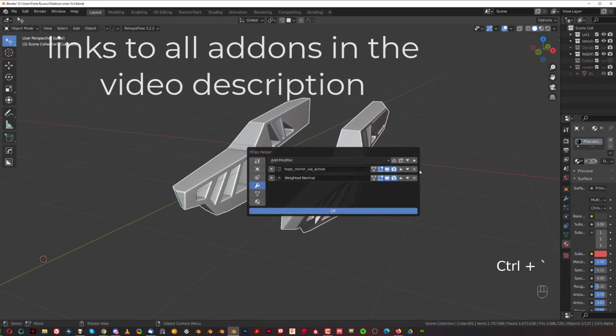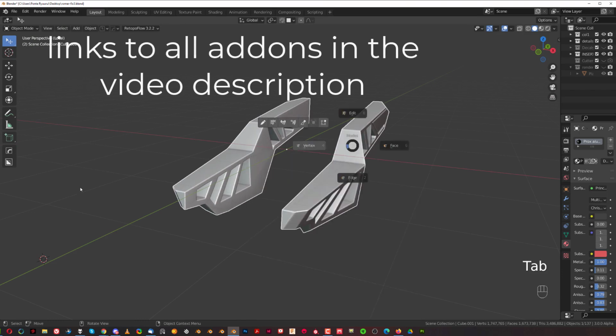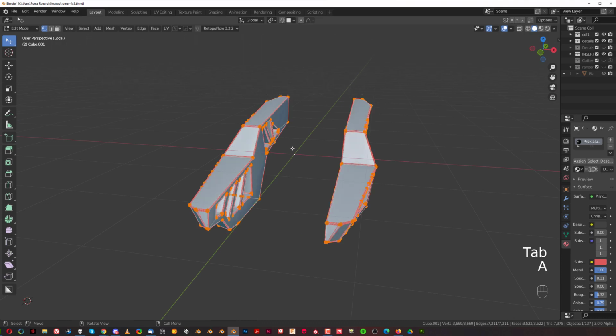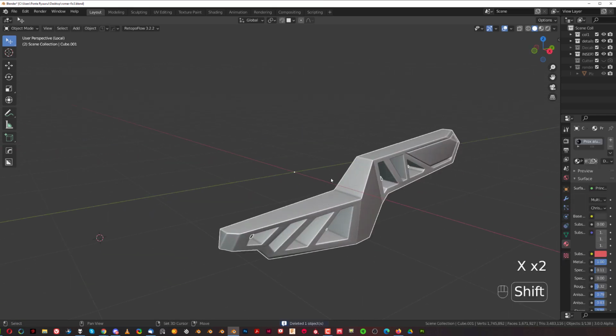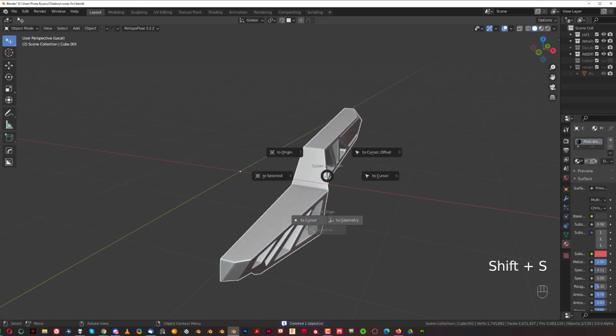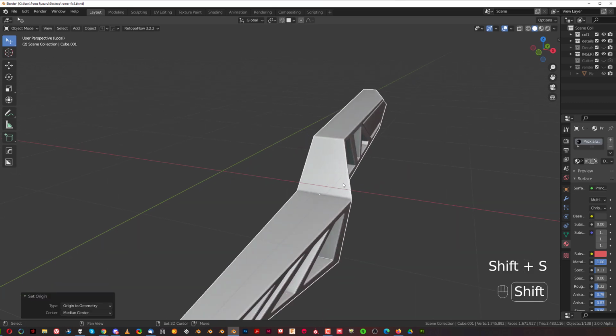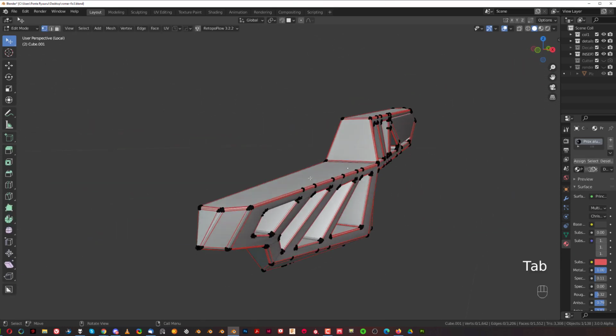First of all, I'm going to remove everything. So mirror in the modifier, I'm going to select everything, press P, and by loose parts, which means I can delete these two guys. And I'm going to select this one and Shift S and move this origin point back to geo, right? So now I'm left with this, and now I can clean it.